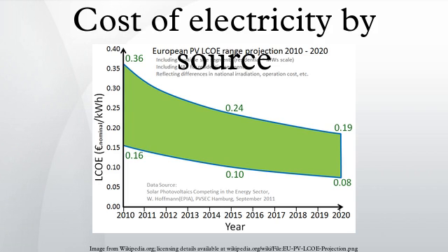Cost factors. While calculating costs, several internal cost factors have to be considered. Capital costs tend to be low for fossil fuel power stations, high for wind turbines and solar PV, and very high for waste-to-energy, wave and tidal, solar thermal, and nuclear. Fuel costs are high for fossil fuel and biomass sources, low for nuclear, and zero for many renewables. Factors such as the costs of waste and different insurance costs are not included. Works power, own use or parasitic load, that is, the portion of generated power actually used to run the station's pumps and fans, has to be allowed for.